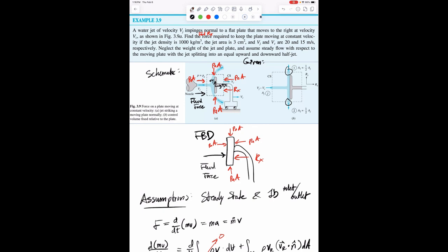yeah, resultant velocity. And the reason this term is important is because we have the speed of the jet, of course. The jet is shooting the water out at 20 meters per second. And when it hits the cart, which is initially stagnant, the cart starts rolling and its speed increases until it gets to 15 meters per second. When the cart gets to 15 meters per second, your jet uses 15 meters per second to catch up to the cart.